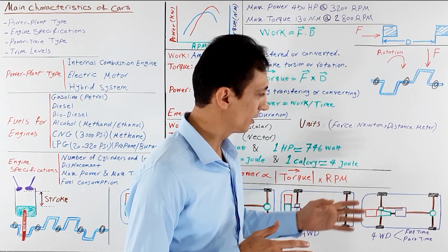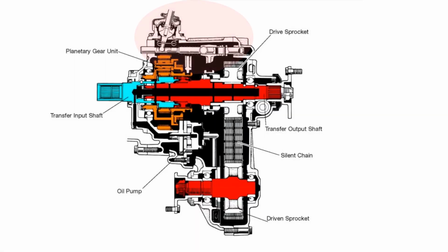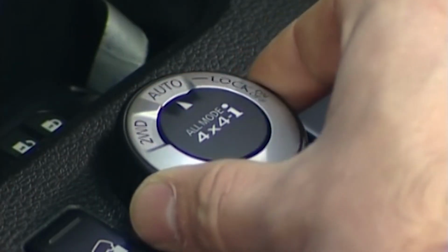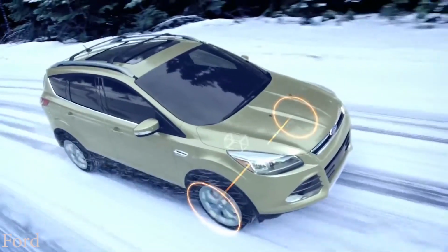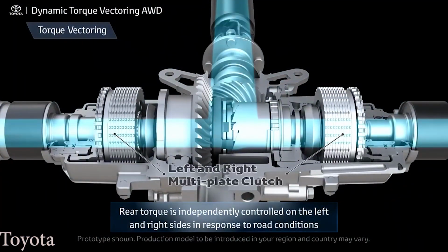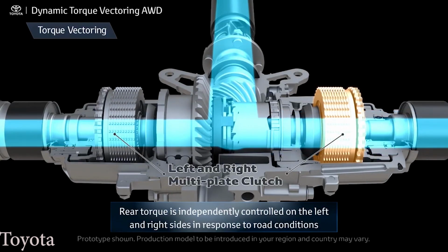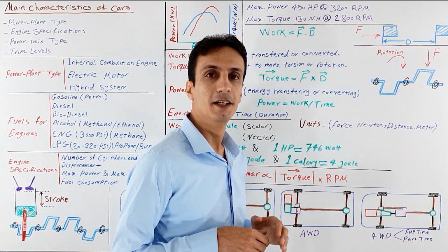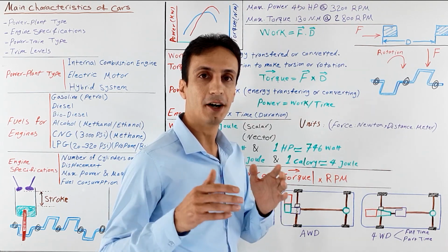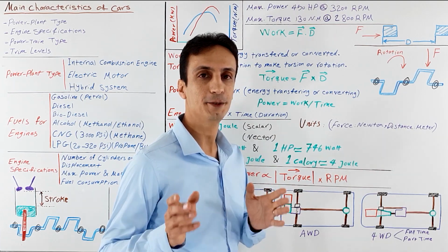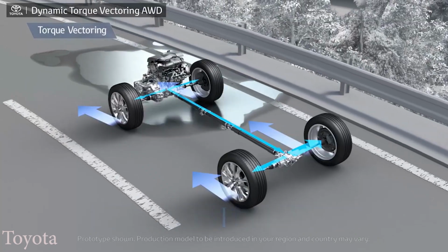Traditional part-time four-wheel drive systems were using mechanical means and gears and chains to select modes and speeds. But modern designs have been affected by drive-by-wire technology, and even names have changed. These systems may be called intelligent all-wheel drive, active all-wheel drive, real-time four-wheel drive, and other names that imply that they are smart cars. In fact, these designs are two-wheel drive systems that go into all-wheel drive mode on demand, and the call is on the computer or computers, as these systems use functions of other modules and computers like the stability control system to do their job.